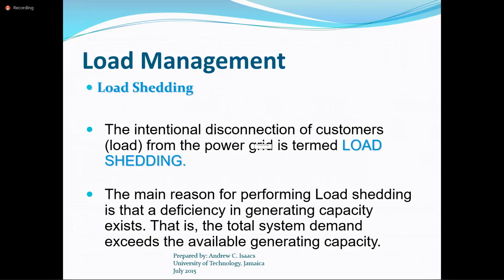Talking about load shedding. Remember I said earlier, the question was raised as to the ability of generators to be automatically dispatched. Instead of doing that, what happens is that there is a removal of generation. Because bear in mind that what may seem like an increase in load can actually be a fault, because the generators are not seeing the load in and of itself.